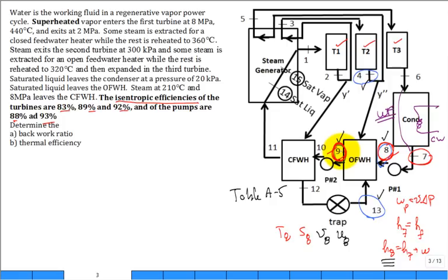All right. What about state 11? Is that saturated liquid? It's not saturated liquid at all. But that's a common mistake students will make. I mentioned it before. I emphasize it. Right? So yes, it's compressed liquid typically.